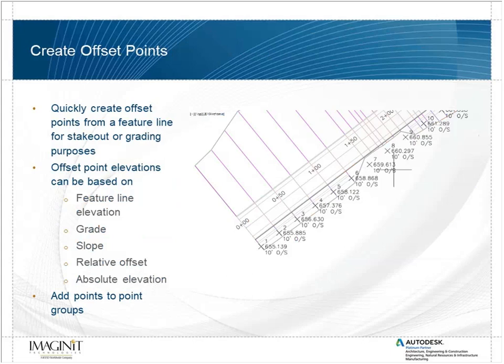When I spec'd this out, as I had intended it to be used, engineers maybe have some roadway design, their corridor model, and all of a sudden, surveyors need to go out and stake that out. But usually in construction like that, we're never actually staking the entity location itself. It's usually at some offset. And there's not a really great, easy way to do that in Civil 3D.